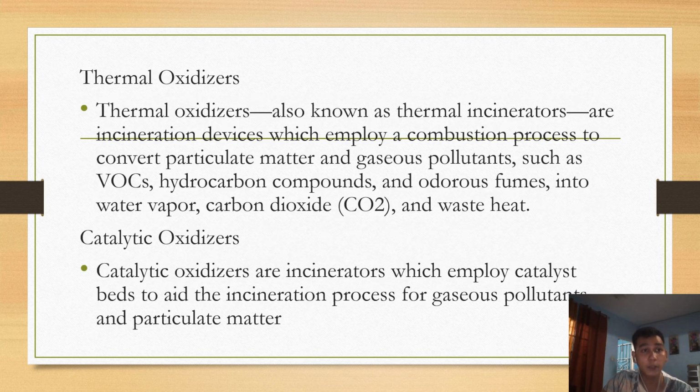Next is thermal oxidizer, also known as thermal incinerators. These are devices which employ a combustion process to convert particulate matter and gaseous pollutants such as VOCs, hydrocarbon compounds, and odorous fumes into water vapor, carbon dioxide, and waste heat. Some types of thermal oxidizer are capable of incinerating air pollutants at 99.99% efficiency.